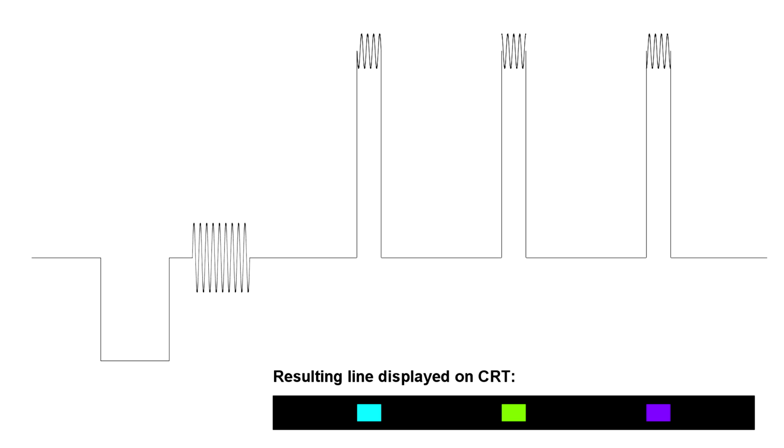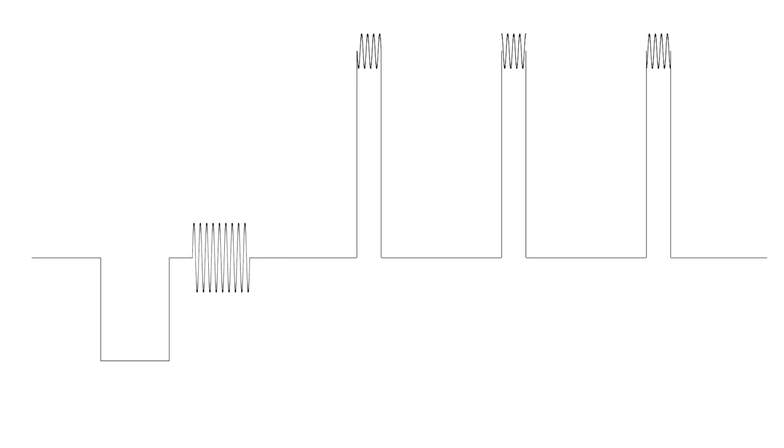So now the fun part. What is it about this design that leads to color glitches? The problems arise when the TV decodes this signal back into its constituent parts, separating luma from chroma. First, what if chroma gets misinterpreted as luma?